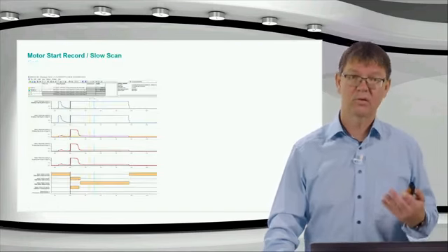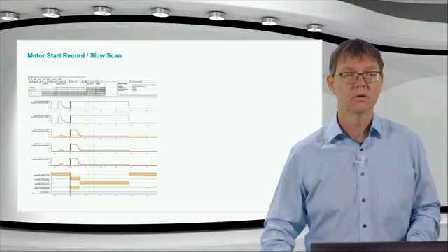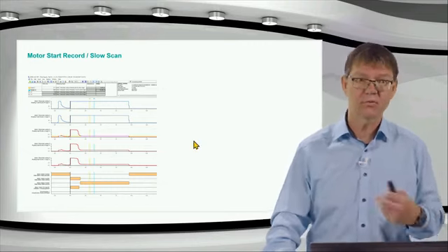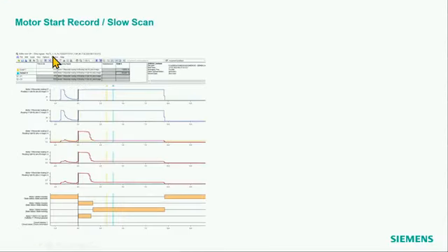Okay, this is how it looks when you watch such a start record with SIGRA, for example. Then I have here the voltages. One voltage is now missing because I wanted to show here also the binary traces and the 3 currents. And this is a special switchover of a motor here, which I had as a COMTRADE file, which I ran on the digital twin.